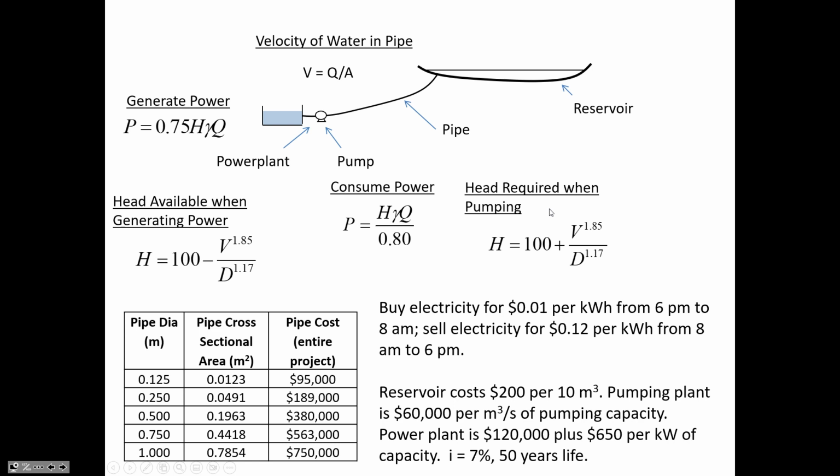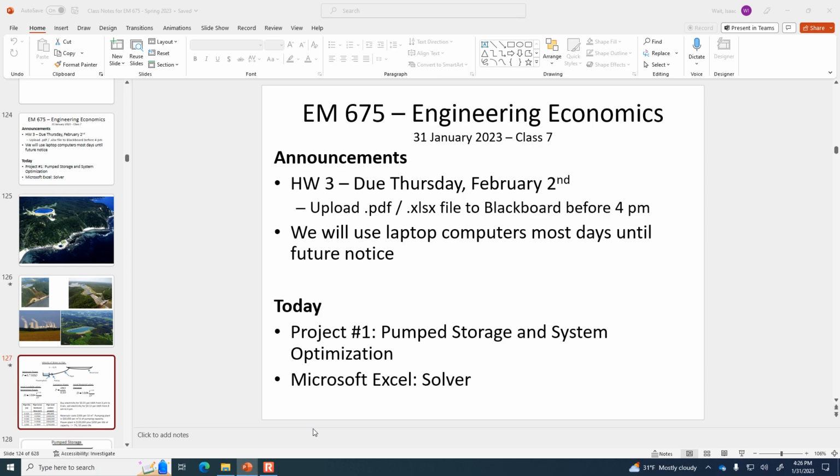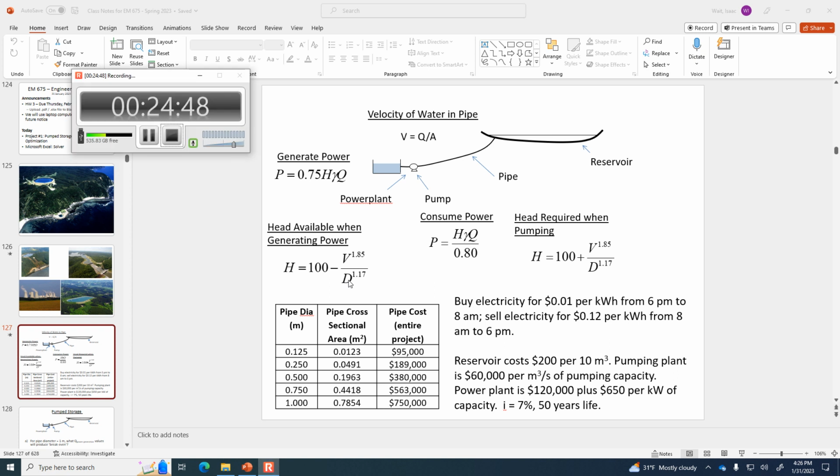So with this formula for gamma, if you're trying to find the number of kilowatts of power that can be generated, you'd multiply the head by 9.81 kilonewtons per cubic meter, and then the flow rate in terms of cubic meters per second. Let me give you that handout right now so you've got it, and I'll give you some time to look it over. I'll pause from talking, and we'll see if there are more questions.